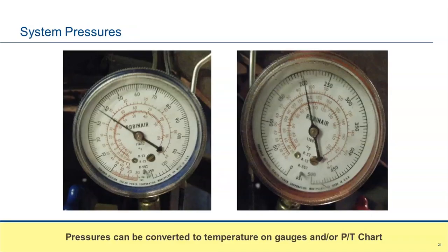I've got a shot here of just some compound gauges, and I usually ask the class, what's wrong with this system? And the answer is we don't know, because we don't know what the application is, and we don't know what refrigerant we're using. What I'm going to suggest to you, this slide is telling us today, because it's not instructor-led, it's over the internet, is if you're living in a pressure world, get out of it. Start living in a temperature world.